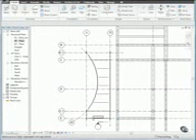Then, click Modify, select the truss, and click the Element Properties drop-down and select Instance Properties. In the Instance Properties dialog, under Constraints, for Start Level Offset and End Level Offset, type -3 feet. Then, under Structural, for Bearing Chord, select Bottom, and under Dimensions, for Truss Height, type 3 feet. Then click OK.